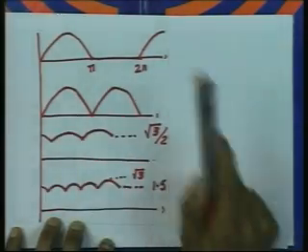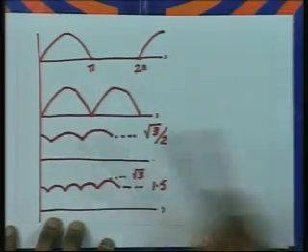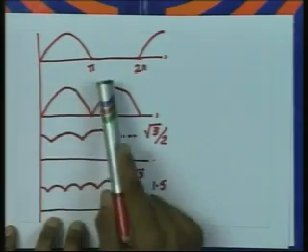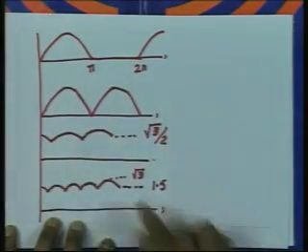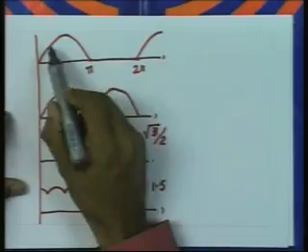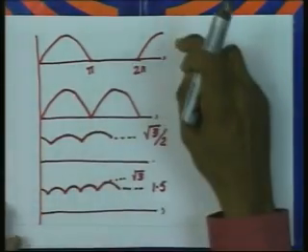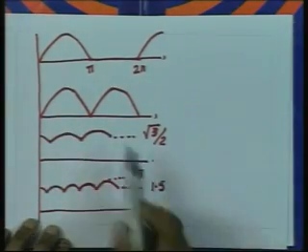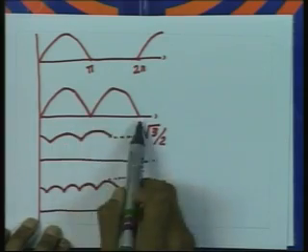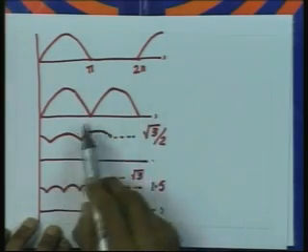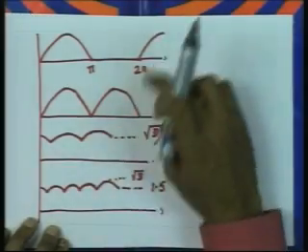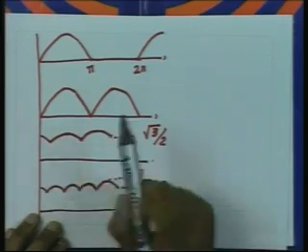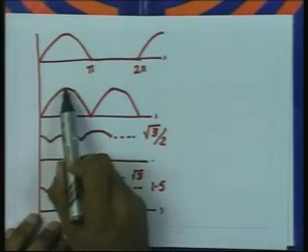In half wave rectification, the filter requirement is the highest, because for 0 to pi the load voltage is the same as the input voltage and from pi to 2 pi it is 0. Now I need to have a constant DC, so my filter requirement here is more, whereas in the 2-pulse converter there is no period wherein the output voltage is 0. So filtering requirement reduces, but the output voltage changes from 0 to Vm.